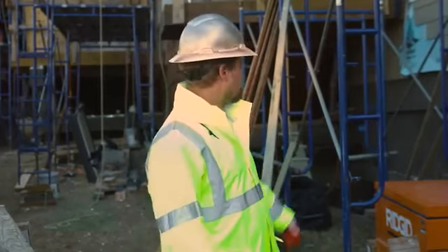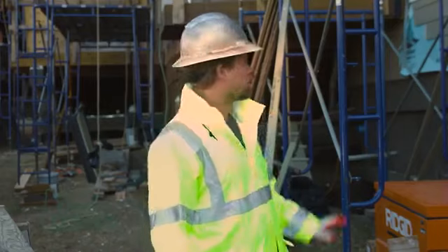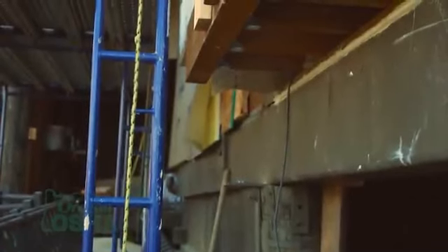Then, once we start building up, we want to make sure it's level. We choose the position where it's best, closest to the building, where we can work and set up properly. And we start assembling. Obviously, it requires about 2-3 people, so one person holds it, another one adjusts it, so we make sure the right guys have proper training for that. And we basically go all the way up. Once we get a couple of frames, a couple of levels, we want to make sure that it's properly attached to the building, and keep going higher.